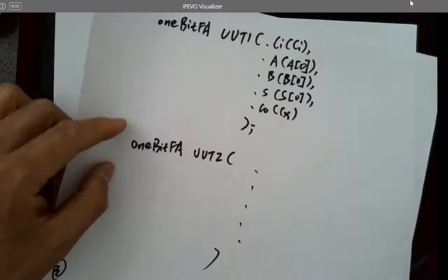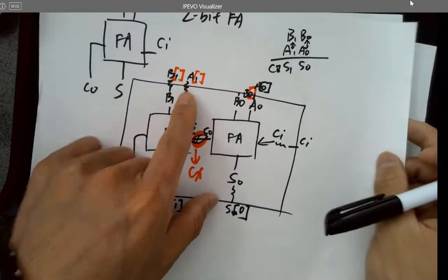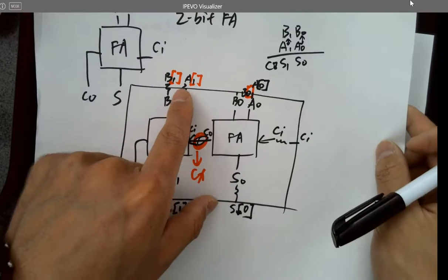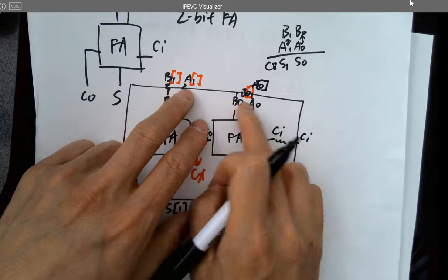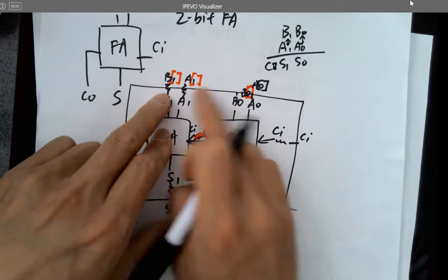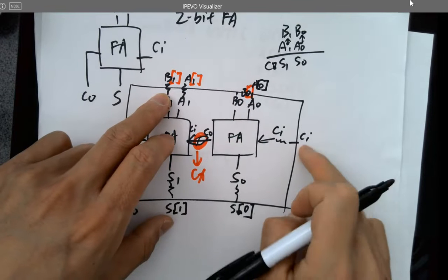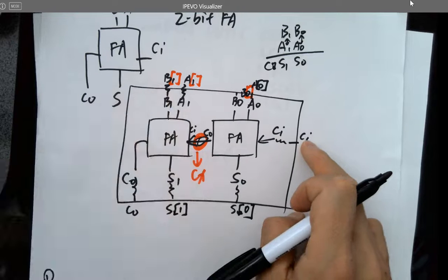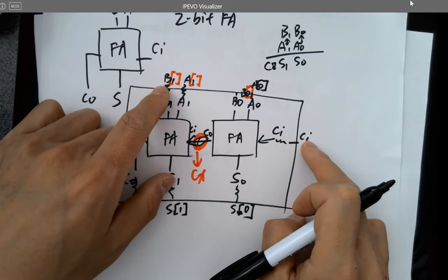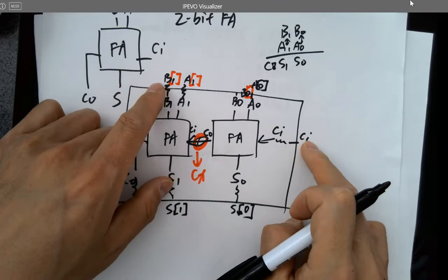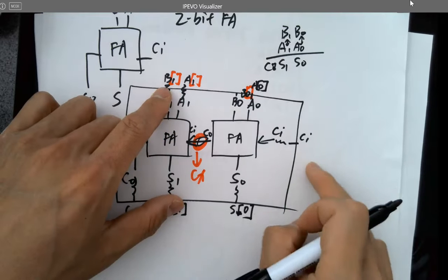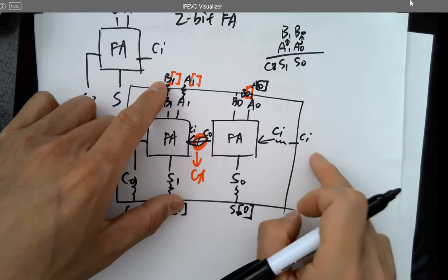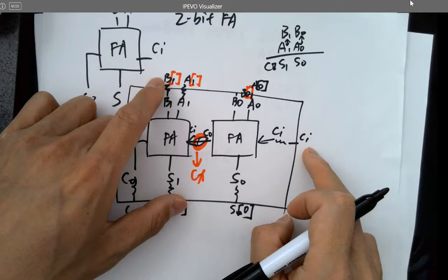So you can combine, because when you are doing the simulation, how many inputs do you have? You are trying to explore all the combinations of the inputs. So it's actually 1, 2, 3, 4, 5 bits as the input. So it's very difficult to list all the possibilities in initial begin, right? You assign values to each one and incrementing by 1 until 2 to the 5th power. So use a for loop instead of listing every single combination.